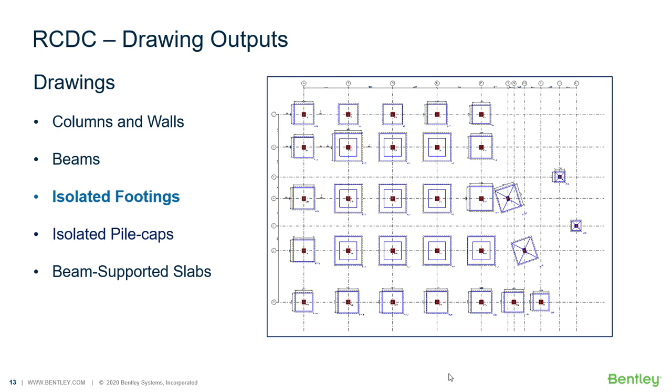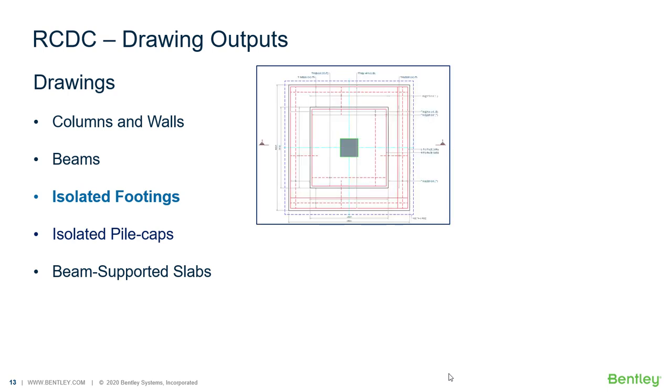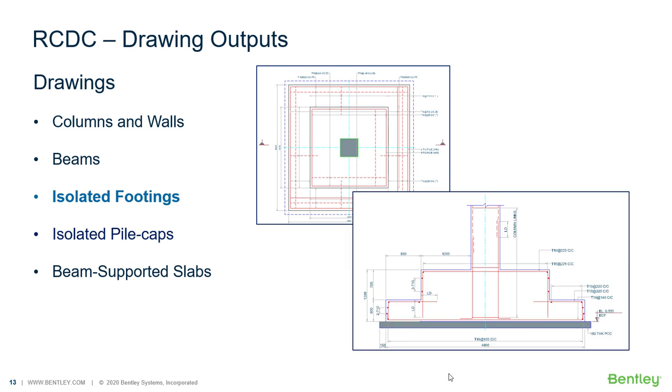For footings, it can generate the foundation layout with PCC marking if you require, including the grids, even if they are not in the analysis. We'll see that in a demo a little later. It can generate the in-plan details for footing or the cross-section. It can handle step footings as shown here, up to 5 steps if required.